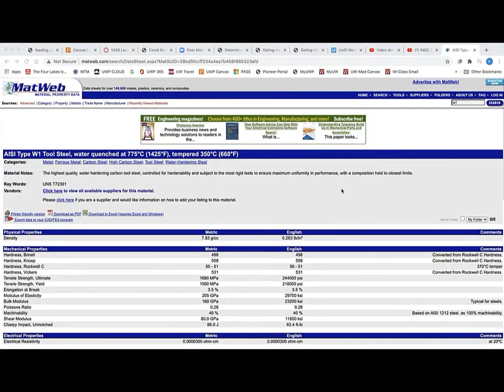Okay, so if you ever watched Forged in Fire, a lot of times they'll use 1080 steel. So W1 kind of gives you a big wide range. 1080 would probably fall within that range. Or you can actually specifically say, I want 1080 steel and get it. And there's 1084 and a couple other ones. But they're all plain carbon steel, and they're pretty forgiving when you forge with them.